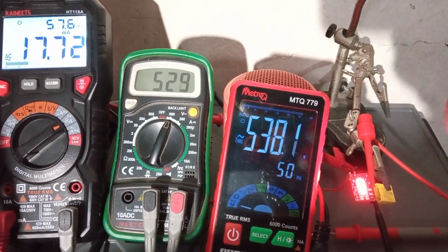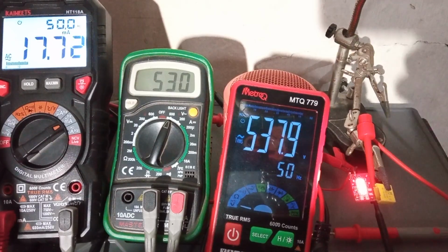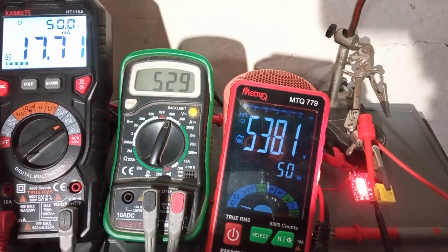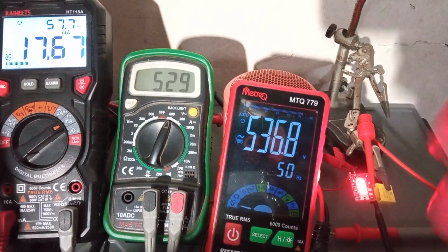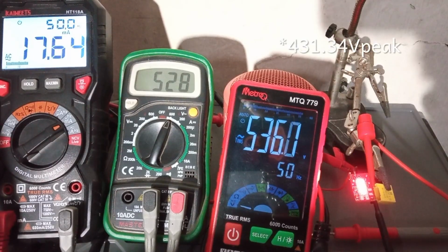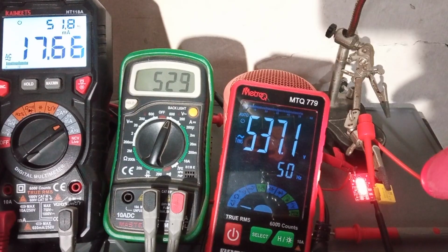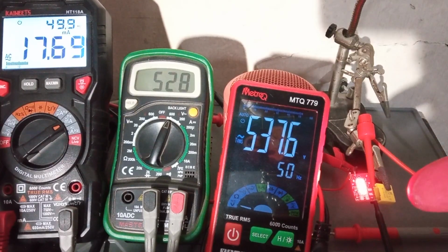So yeah, you can really run capacitive droppers from 50 volts to 537 volts and nothing will go wrong. And if your actual target is around 500 volts, something like that, use a capacitor that can take that voltage. And currently this capacitor is rated for 310 volts AC, which is like some 400 something volts peak. So the peak voltage is something that matters. Because this is rated for AC, they have already calculated the peak, so we don't have to worry about that.